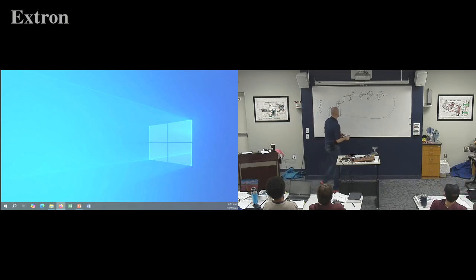Parker Miller. Now, if I go from here to here, I already erased my 3s. I changed my circuit. What am I going to get? I broke the wire here. 0, yeah, because my positive voltage goes through the light bulb and through the light bulb, and we're not going to have any amp draw. There's no amp flow because it's an open circuit.